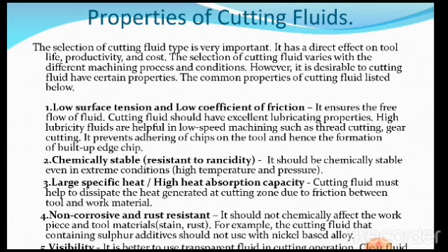The common properties are low surface tension and low coefficient of friction. It ensures a free flow of fluid. Low surface tension means what? It has to move freely. It should not stick more to either the workpiece or the cutting tool whenever that cutting fluid is used. Cutting fluid should have excellent lubricating properties.